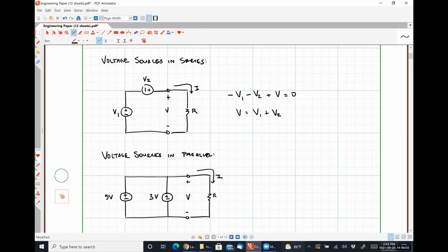what if I have this situation? What voltage is my resistance? So after 3, the average for, the correct answer is how the hell should we know? We've broken the laws of our circuit analysis, right? Yeah, they're in parallel with different voltages. That doesn't work. So if you see anything like this, you can't actually solve it using circuit analysis techniques.